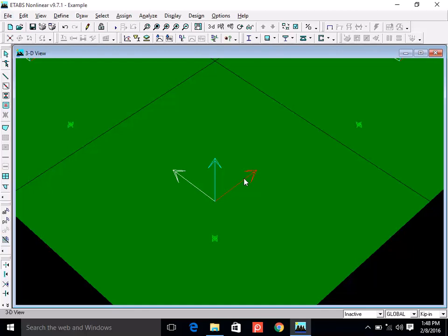Okay. But in case of finite element analysis, you will see that it may always give some contribution to the other direction, even if it is one way. When we say one way, perfectly one way slab, a 4-sided supported slab is not 100% one way, although the dimensions say that it is one way. Yes, a 2-sided supported slab is perfectly a one way slab.